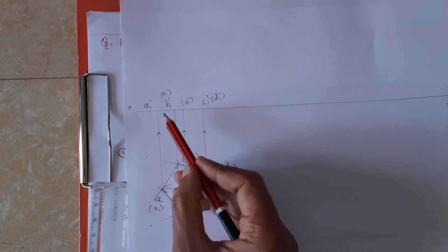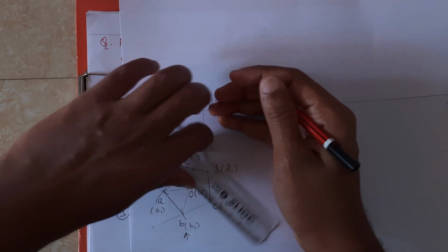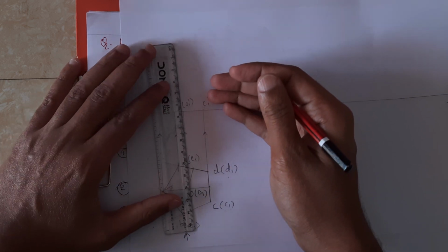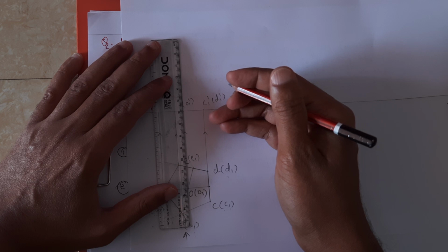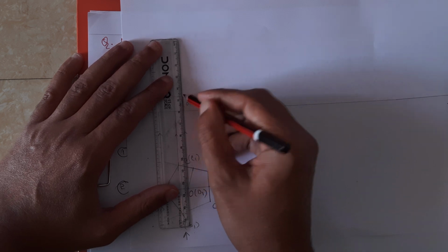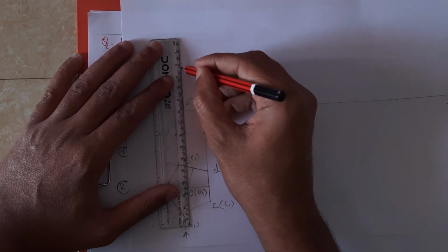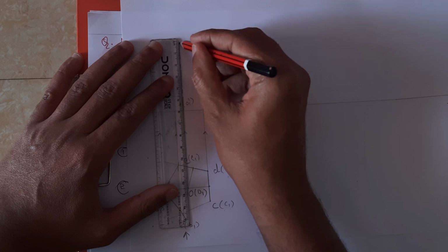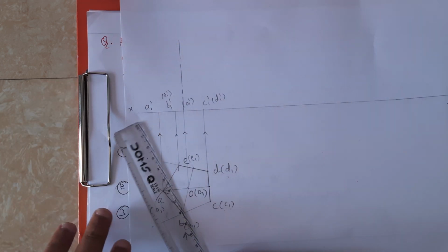So this represents what? The bottom face. Whereas, what is the length of the axis? It is 60 mm. So take the measurement of 60 mm. How to represent the axis line? One large line followed by a small line, thin line. Okay, large line, small line, large line, small line. So this is how we are going to draw the axis.